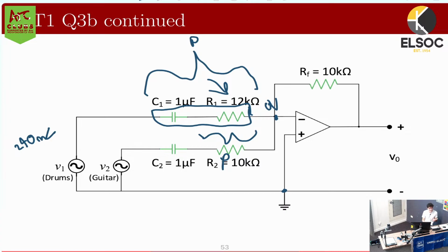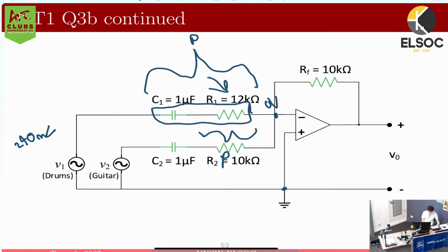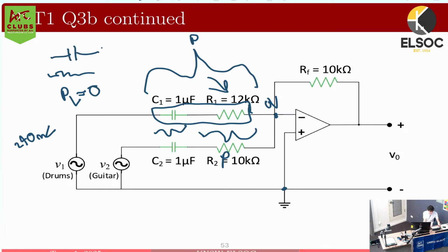No? Okay. Well, the reason why is because the average power for any reactive element is always 0. So if you have an inductor, the average power through that inductor is always 0. If you have a capacitor, the average power through the capacitor is always 0. So if the power of all of this is whatever we found, that means if we look at it component-wise, this contributes 0 power, so all of it has to come from the resistor, if that sort of makes sense.